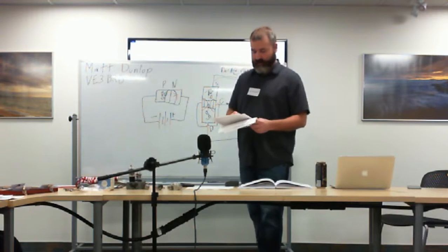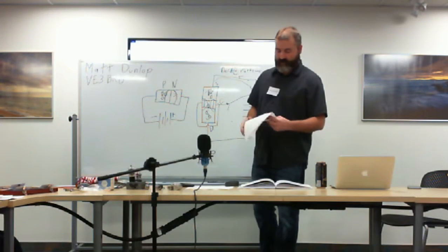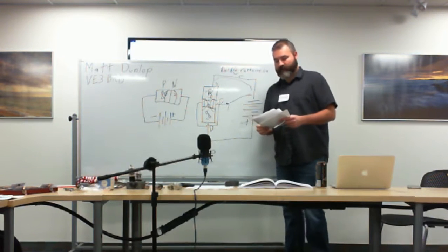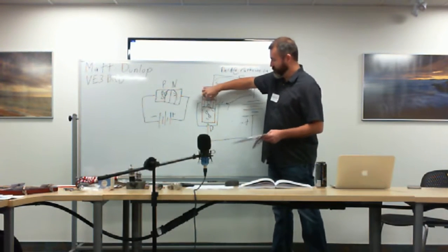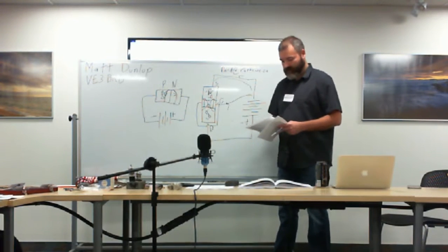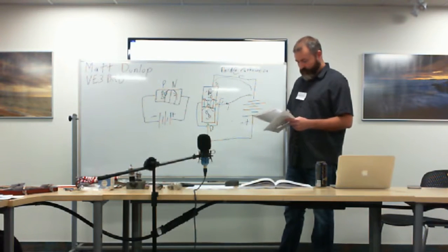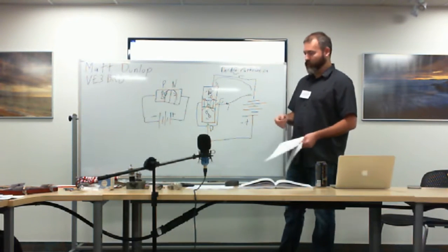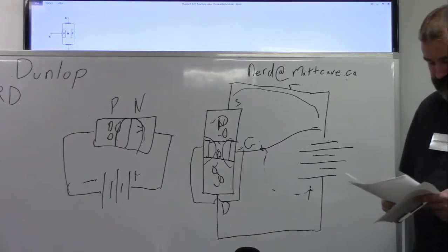So again, I highlighted some things on this page that answer questions on the test. To reduce the current flowing in a FET, you increase the reverse bias voltage on the gate, which causes this pinching to actually happen, which stops the flow of electrons through. When it's reverse biased enough, it's called the pinch off voltage, because it pinches it off.